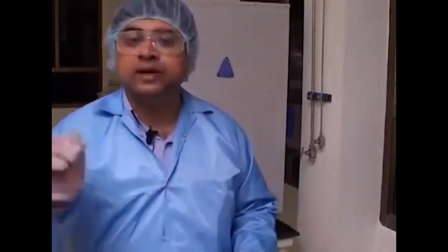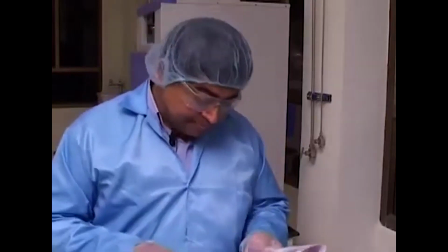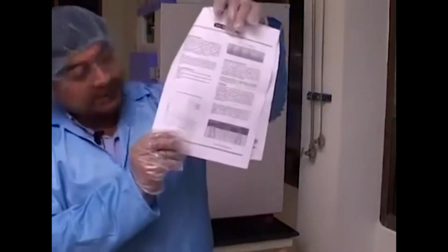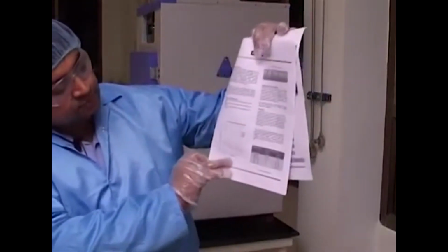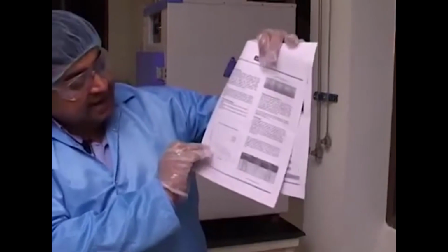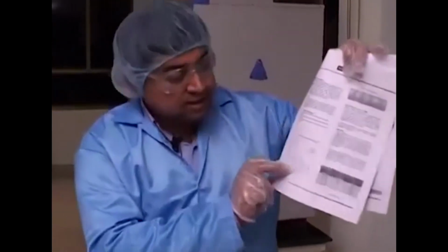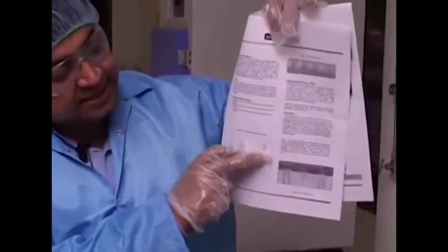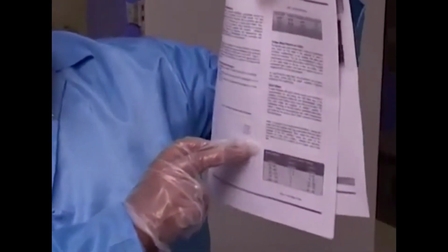So essentially I would like to go ahead and make features which are about 20 to 25 microns thick. And for doing that, if you see this resist grade sheet, you basically get these curves where it talks about what is the RPM on the x-axis here, and what is the corresponding film thickness that you will be getting. So when we are using a certain grade mentioned in this table, SU8 2025, which is the lowest grade here, is really corresponding to the lowest curve. And corresponding to about 20 to 25 microns, we find the RPM that we would need is close to 3500 RPM.